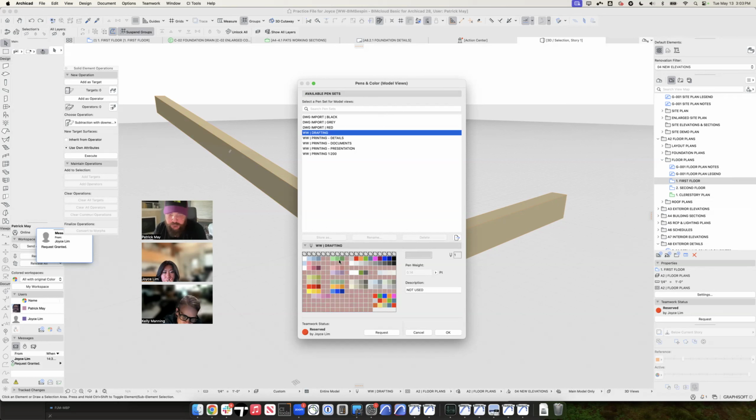All of these pens that are groups of three, this is sort of old school AutoCAD pen logic in a way. It doesn't necessarily make sense in terms of graphic standards, but they're pen groups based on their function. But they're all the same three pen weights. If we look at what they are, it's 0.05 millimeter, 0.15 millimeter, and 0.3 millimeter. And that's the case with all of these pen groups of three. They're just used for different functions.